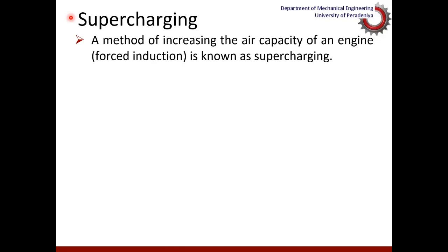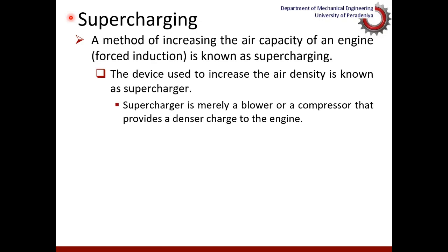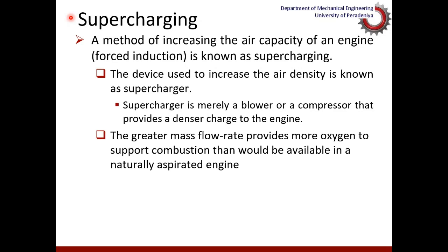Now, if you concentrate more on supercharging at the beginning, that is a method of increasing the air capacity of an engine. The device that we use to do that is more or less known as the supercharger, which is merely a blower or compressor that provides a dense charge into the engine. So as I said earlier, more fuel could be burned if you increase the density, because the air-fuel ratio is calculated based on the mass, not the volume.